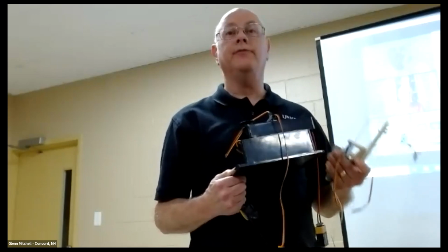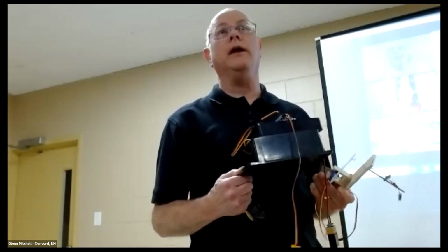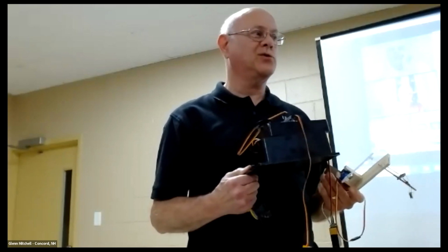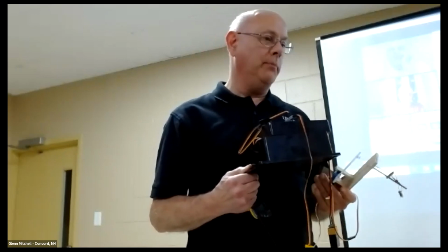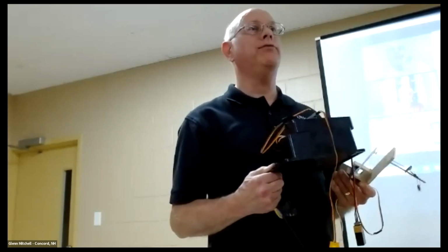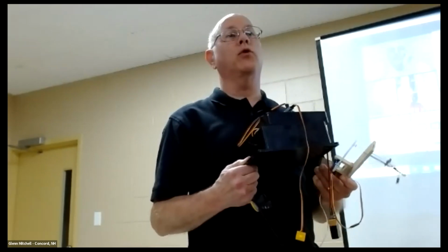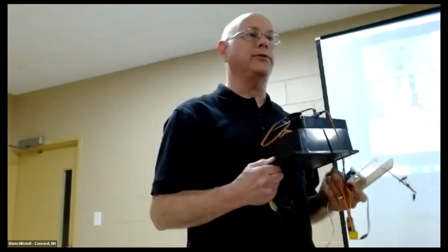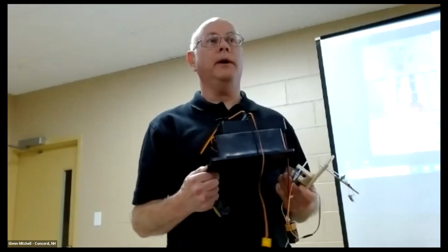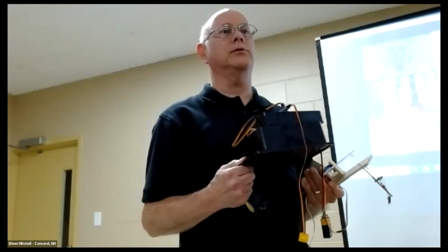I can't say enough about these Wago connectors because they're just so convenient, so easy, and they work from about 20 to about 12 gauge wire. Actually, I think I put 24 or 26 in them with absolutely no problem. And that's what I use for track drops to the bus. Because my bus is, I think, 16 gauge, and my track feeds are about 26.